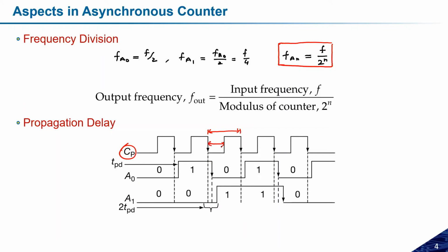So whatever the delay of the flip-flop we have, that should be within this limit only. If I increase the third stage, it may start from here, the fourth stage will start from here, and it might cross this limit. So it can also limit how many stages I can consider in the asynchronous one. Let me repeat what I'm saying. This is really very important.